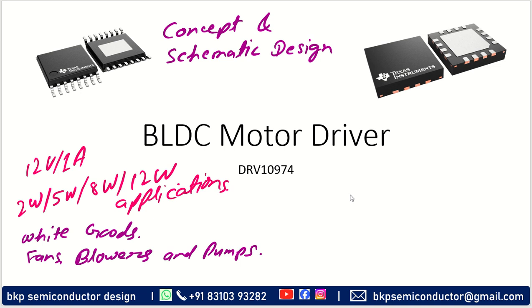So what we will do is we will take up low power BLDC motor driver applications, and in this we will try to understand how a BLDC motor driver circuit can be designed and how we can make it very useful for our low end applications, let's say white goods or fans or blowers or pumps, all these things. So basically one of the ICs we will take is the DRV10974, and this will be applicable for applications up to around 12 volt, 1 ampere ratings.